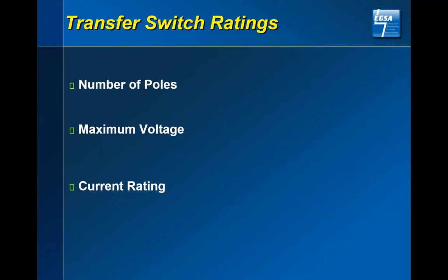The current rating of the transfer switch, and I've been questioned on this a little bit, but the transfer switch needs to be able to carry its capability, whatever it's labeled for, 600, 800 amp. It needs to carry that continuously 24 hours a day, 7 days a week, so on. When you look at a circuit breaker, one of the most common ones is referred to as an 80% rated circuit breaker.